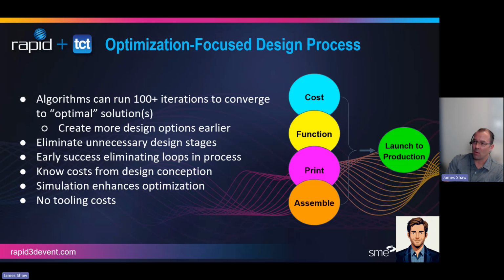We've got these algorithms, if you will, topology optimization and generative design, that include some of the requirements for manufacturing, especially since we have different processes, right? So we have powder bed fusion, we have DED. Those have particular requirements with respect to the machine, the speeds, and those are all incorporated now into our DFAM tools.